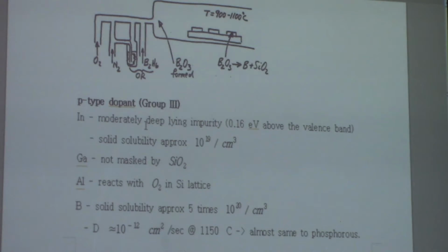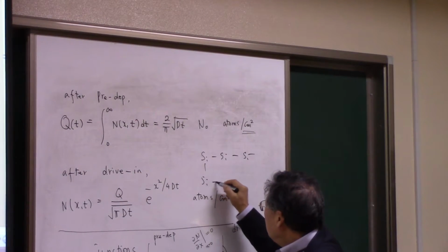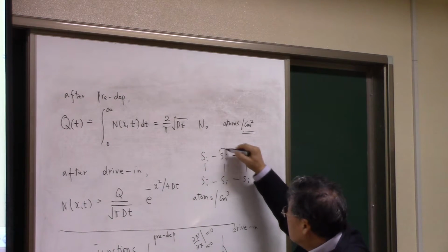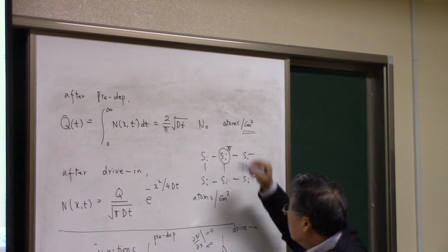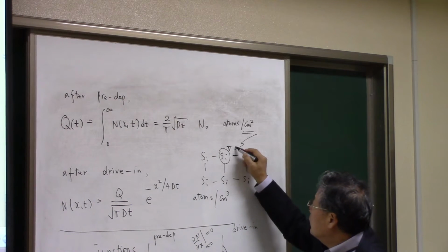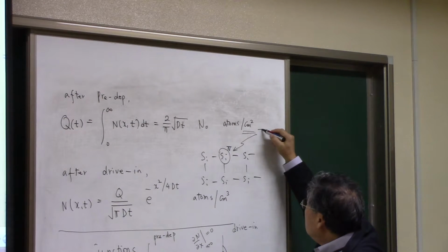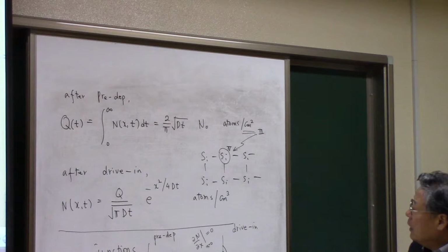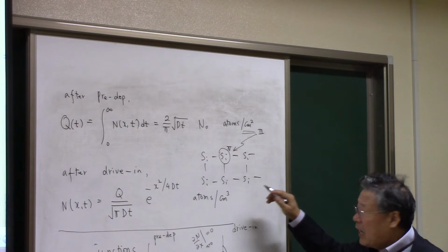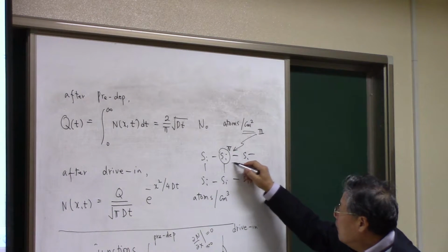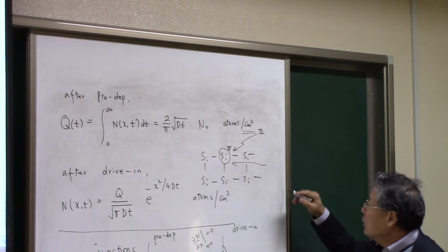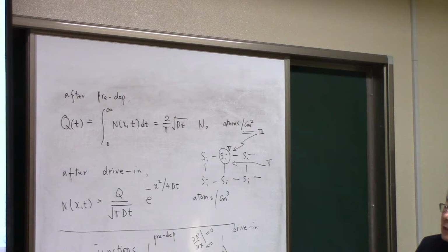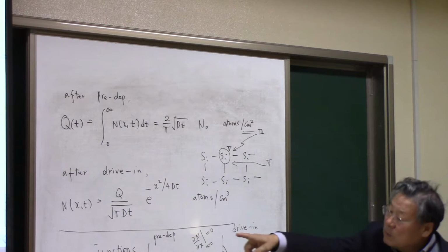So for the silicon covalent bonding system, if you want to dope p-type, then this 4-valence electron material has to be replaced with 3-valence elements like indium, gallium, and boron. And if you want to dope the silicon as n-type, then this silicon has to be substitutionally replaced with the 5-valence electron elements, which is going to be shown in the next slide.